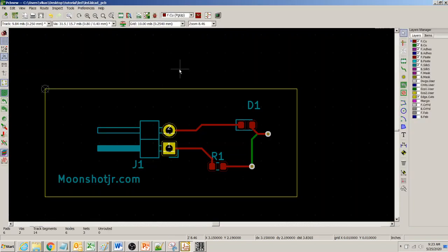But one caution is, if this is the first time you are generating a PCB file, I would suggest that you start with a really simple two-layer board, just to make sure that you are doing it right, and send it out, and make sure that when it comes from the PCB house it looks good to you, so that if there is any error, you lose only a small amount. And once you are confident about it, then go ahead and do more complex PCBs like 4 layers or 10 layers and more. I hope this helps you, and thanks for taking a look.